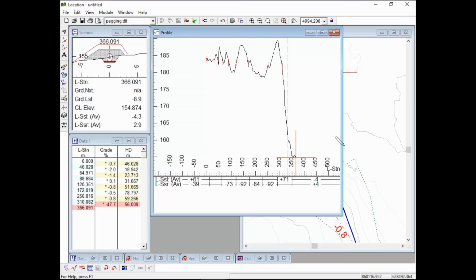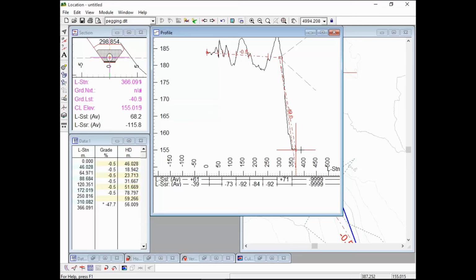I've got a decent profile here. Now I can start designing it. And of course I can do this by hand, but we want to show you the optimizer. But let's just quickly do it by hand, see how it works out. I'm going to put in a grade like so, and another one down like that. And I like the 2 endpoints because I've designed them properly.